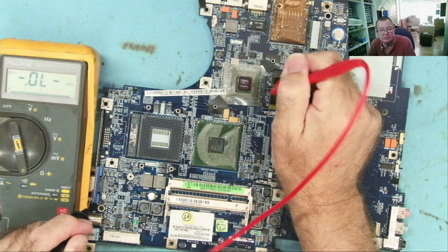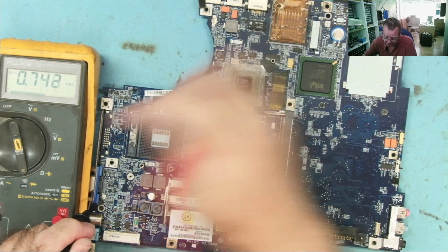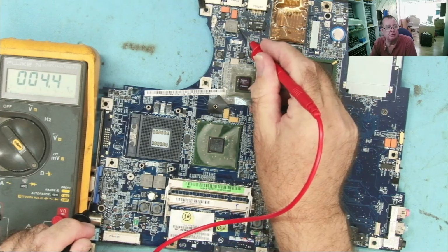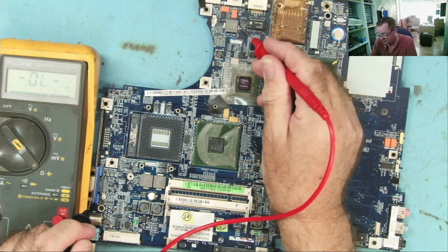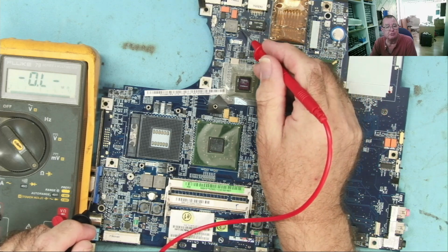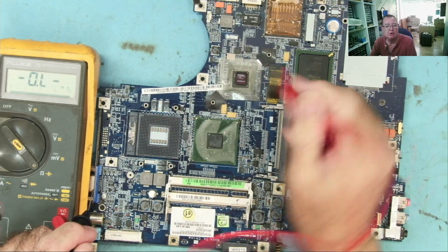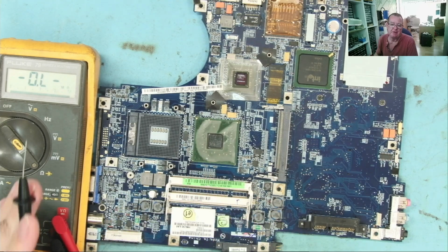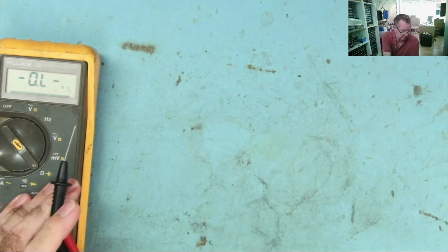This is probably powering this GPU, by the way. Looks very much like a short. Let's go to resistance. No, it's not a short, it's 4.3 ohms. That's fine for a GPU. So that's why you shouldn't use diode mode whenever you're measuring off these inductor coils. Always use resistance mode, because if you don't, you'll think they've got shorts where you haven't.